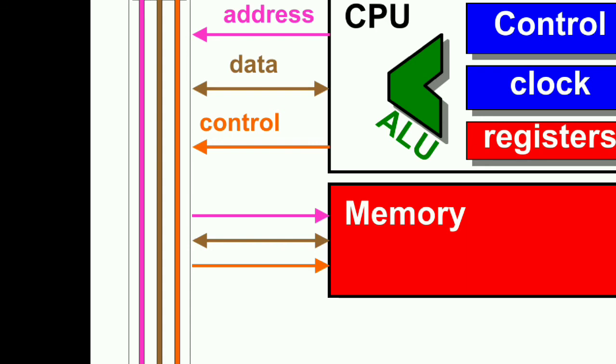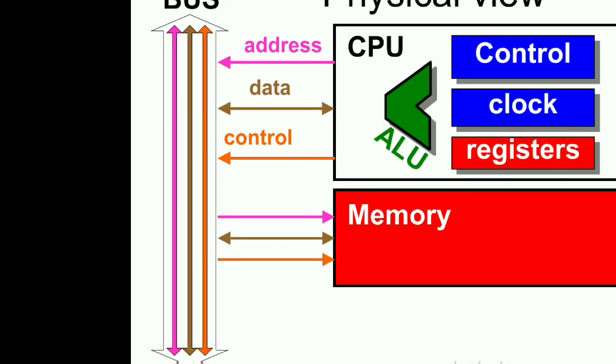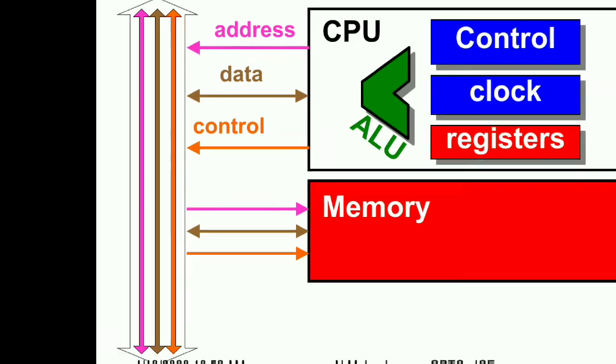One more point to highlight: the address bus and data bus are actually buses, functionally a group of wires. That means you cannot access the bus as an individual wire. Whereas the control bus is actually not a bus. It is not a group of wires, rather it is a group of single wires. That means control signals can be accessed individually: read command, write command, and many other commands, depending on the complexity of the processor.